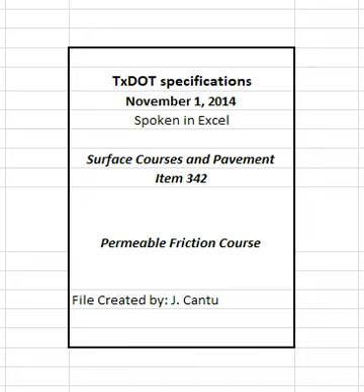2.2 Baghouse fines. Fines collected by the baghouse or other dust collecting equipment may be reintroduced into the mixing drum. 2.3 Asphalt binder. Furnish the type and grade of binder specified on the plans that meets the requirements of Item 300, Asphalts, Oils, and Emulsions.